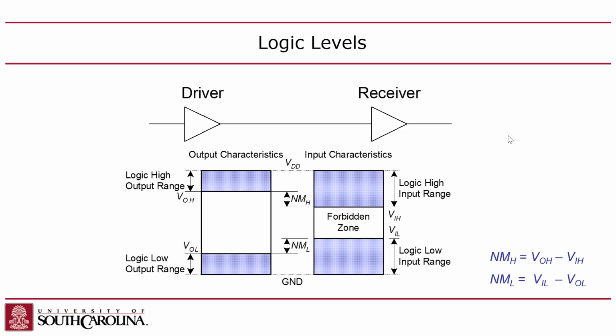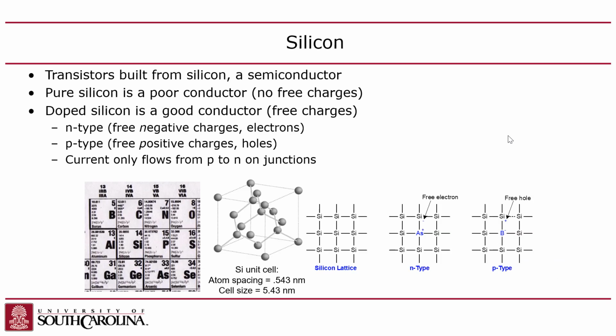Yeah, so the idea is that you can add noise here to this input, right? Which will add some noise to that output, but it will reduce the noise, right? So then I can still add extra noise here to this middle wire before it gets to the receiver. That's the idea of the noise margin. Does that make sense? So basically, it's essentially the amount of noise you can tolerate on your wires. Okay, any questions about that?